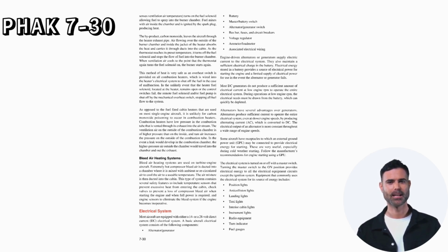This method of heat is very safe as an overheat switch is provided on all combustion heaters, which is wired into the heater's electrical system to shut off the fuel in the case of malfunction. In the unlikely event that the heater fuel solenoid, located at the heater, remains open or the control switches fail, the remote fuel solenoid and/or fuel pump is shut off by the mechanical overheat switch, stopping all fuel flow to the system. As opposed to the fuel-fired cabin heaters that are used on most single-engine aircraft, it is unlikely for carbon monoxide poisoning to occur in combustion heaters.